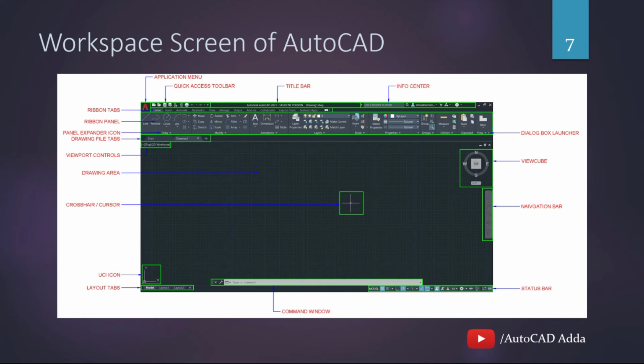This is a navigation tool which becomes active when a cursor or the crosshair is positioned over it. It is displayed when you are working in 2D or 3D working space. In 3D, you can view your drawing from different angles. It also has a compass which is displayed below the view cube. While working, you can click on any direction to view your drawing. It has a rotation direction on the top right corner which rotates the drawing by 90 degrees. The home button provided on the top left side brings you to the default southwest isometric view.